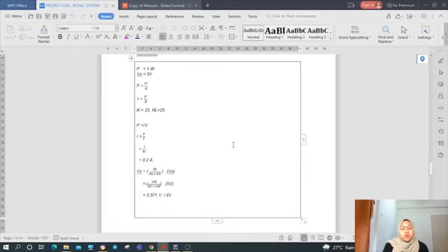I would like to present my part, which is voltage regulator and load. Voltage regulator is the component of a power supply that ensures a steady, constant voltage supply through all the operating conditions, and the output voltage remains the same even if the input DC voltage varies or the output load connected to the DC voltage changes. For this project, we are requested to construct a voltage regulator of type op-amp shunt regulator circuit with the given specification of 5 volt as the output voltage.